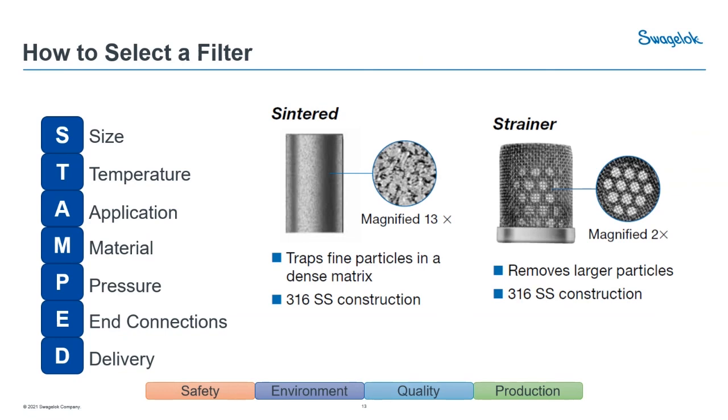And if that's too laborious, you may even need to reevaluate the micron size being used. Perhaps your particulate could be larger than the micron size that you need, and you could go a step up in size there. So keep that in mind if you're having some abnormal pressure drop or reduced flow downstream of that filter.